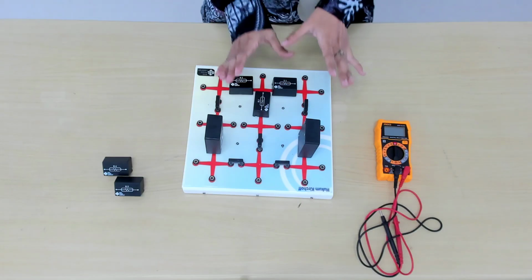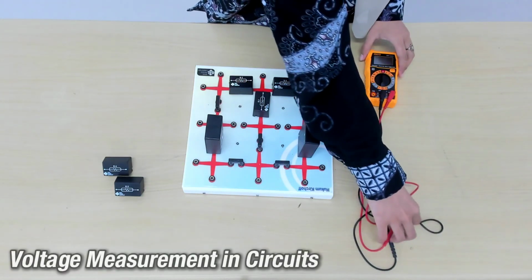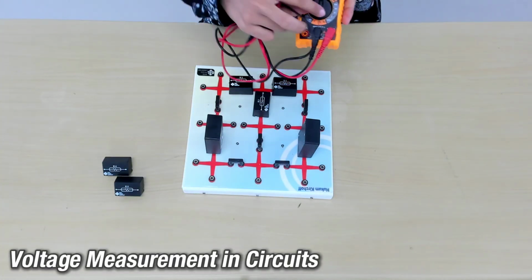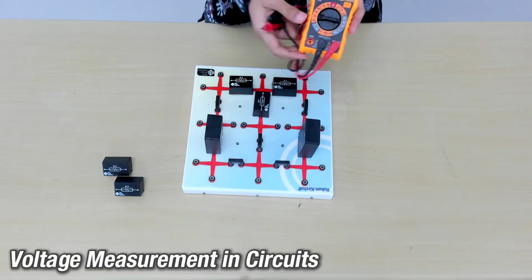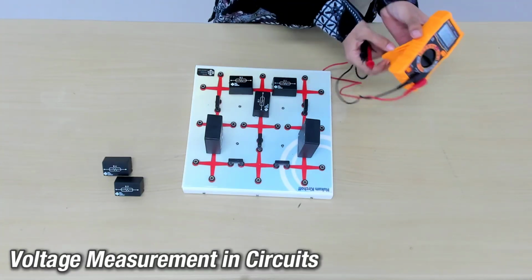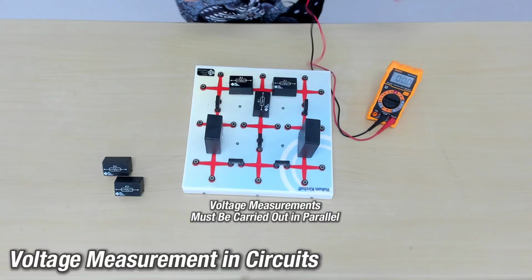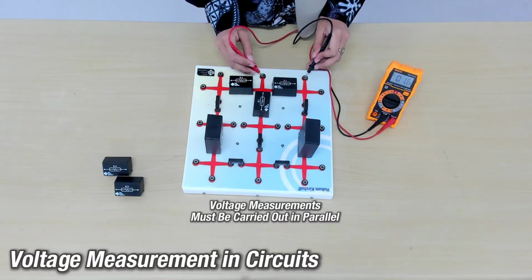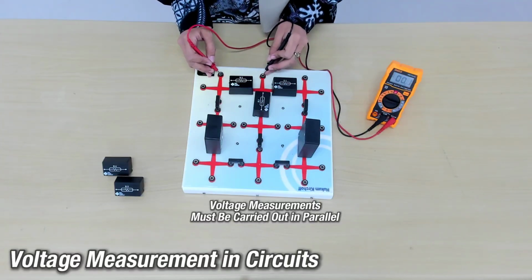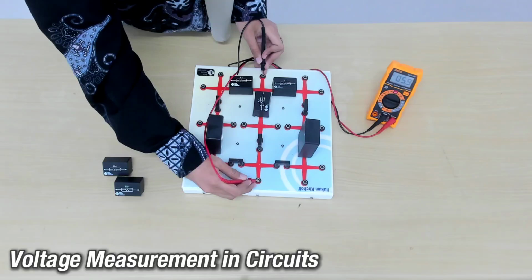Okay, to measure the voltage and current, we use our digital multimeter. First, turn the dial to the DC voltage reading and insert the probe into the breadboard hole in parallel for each component like this. For R1, for R2, and this is for R3.